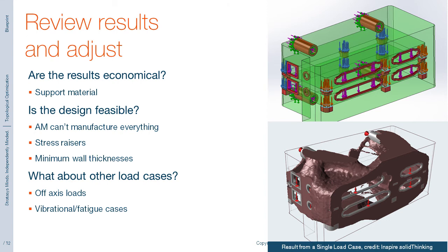And finally, just like a regular FEA simulation, it's important to consider a range of load cases to produce a balanced design, as unfortunately it's quite rare that a component is operated under such a pure single load case, so we might need to repeat this simulation for some others.